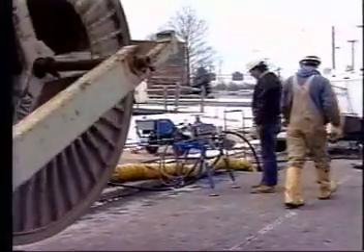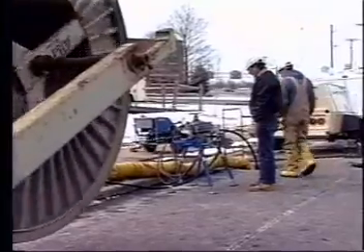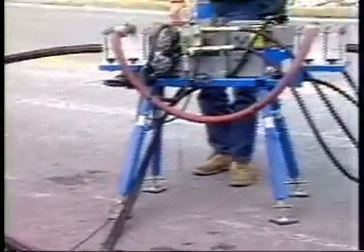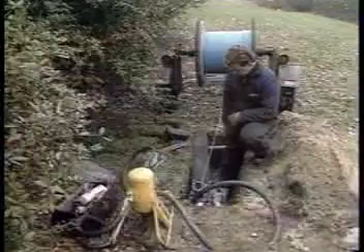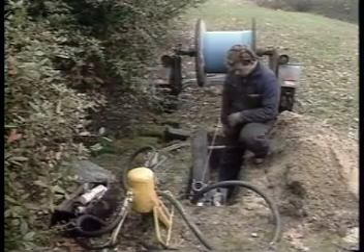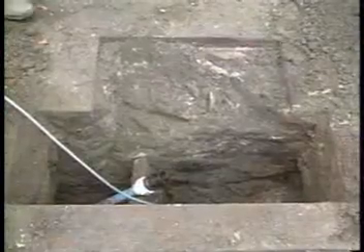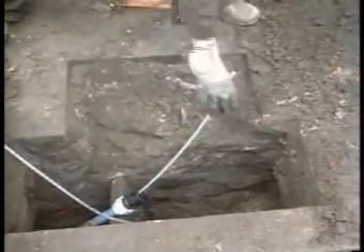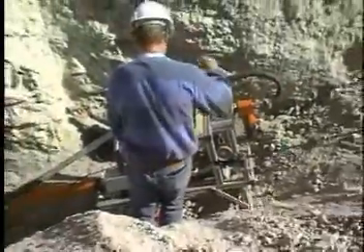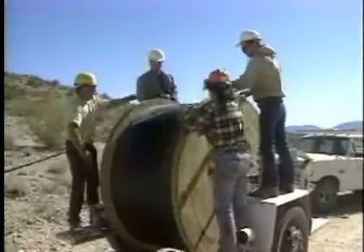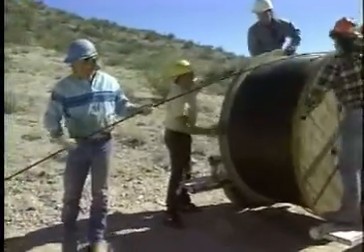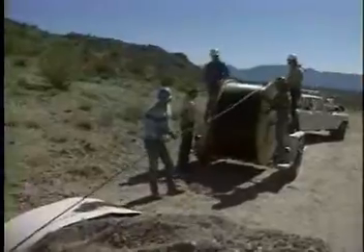The drag forces are distributed along the entire length of the cable, eliminating the tensile forces concentrated at one end of the cable during conventional pulls. The distributed force on the cable is just high enough to overcome friction and is so small that the cable can easily be stopped by holding it with one hand. As a result, fiber stresses are reduced to near zero during installation. Because of zero pulling force, there is no need for large or steel tension members to be present in the cable, allowing the use of smaller, lighter, and less expensive cable types, and no pulling ropes in the ducts.